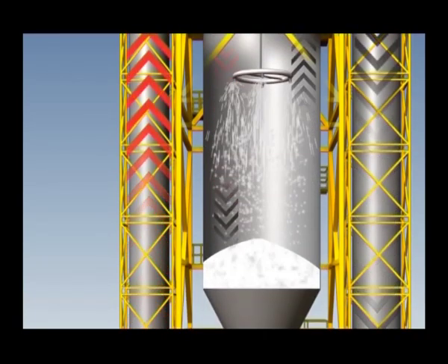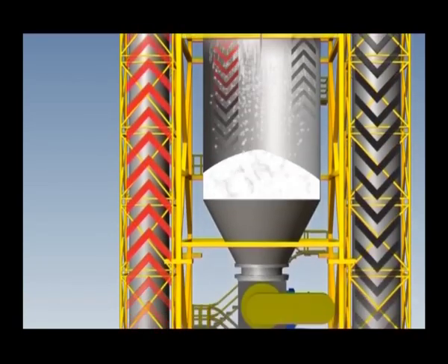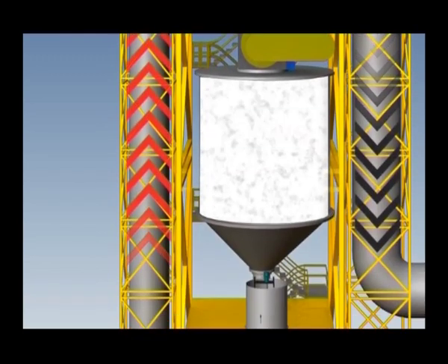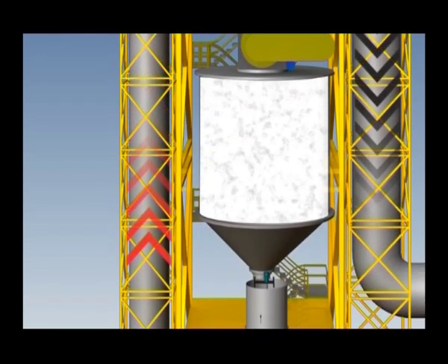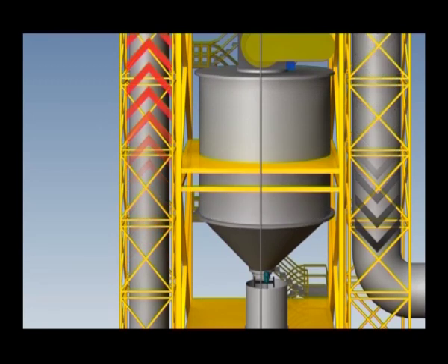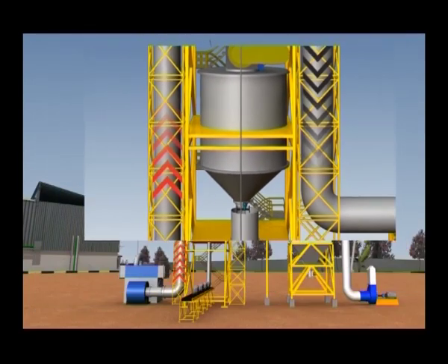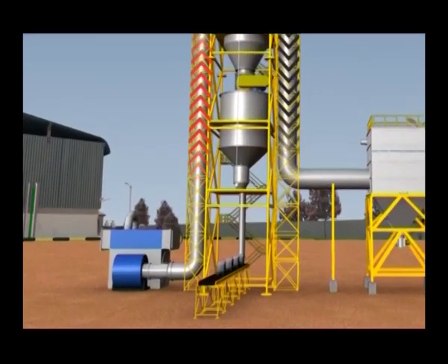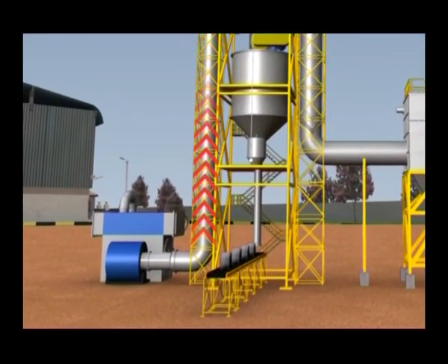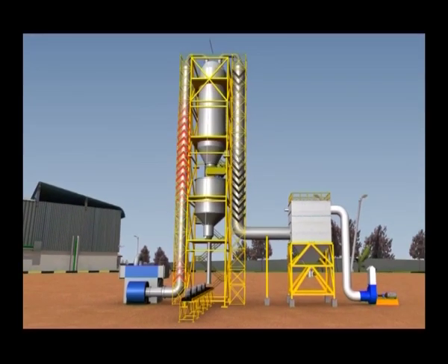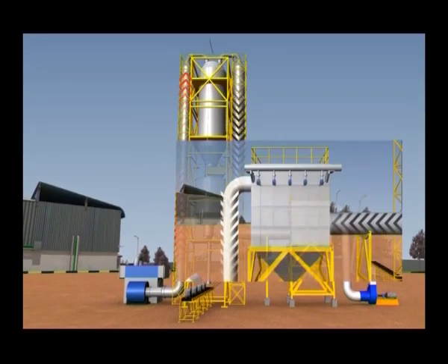or counter-current mode. Although the drying occurs at wet bulb temperature, the dried powder sees higher temperatures while it is pneumatically carried by hot air till the exit of the dryer, just before it is separated in a cyclone from the hot air and collected into a bin. Hence, the hot air temperature at the exit also is an important parameter that is to be paid attention to minimize the heat damage to the product.